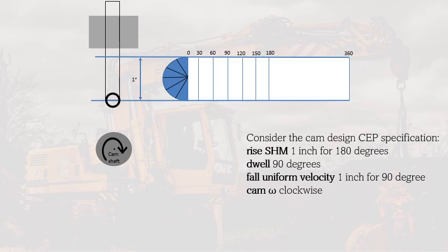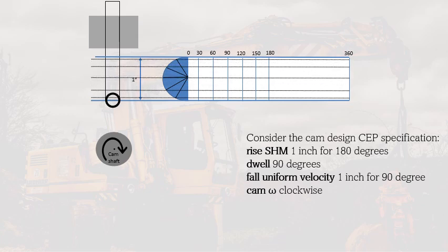These divisions would represent this division that you can also see here in the axis. Then after that, we are going to draw a horizontal line from the intersection of this division to the circumference of this semicircle. The intersection of this horizontal line and this vertical line would represent the stroke or the displacement of the follower.